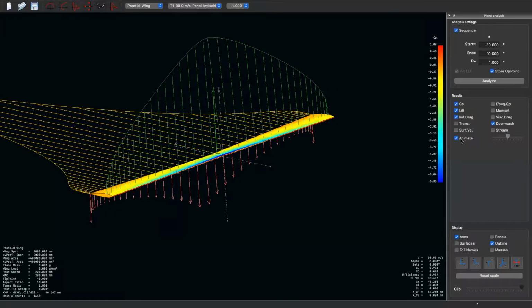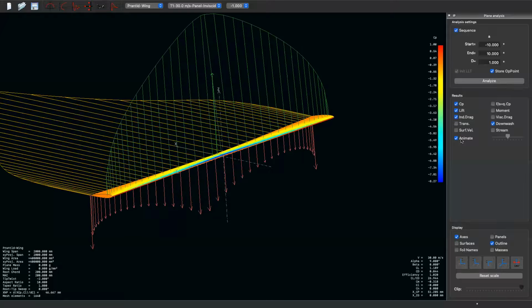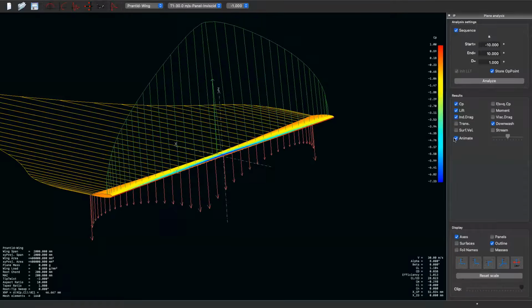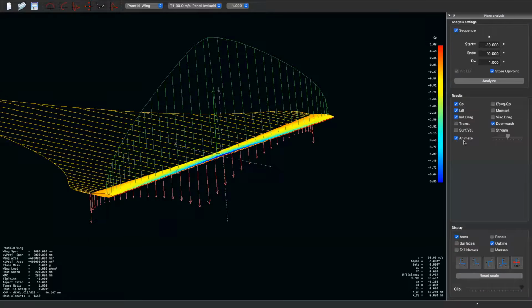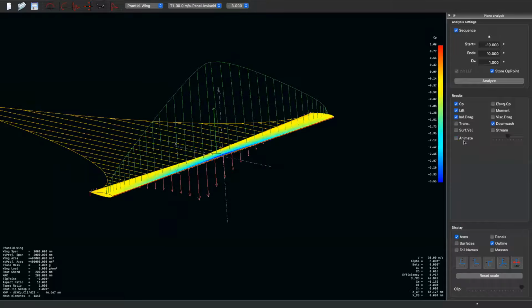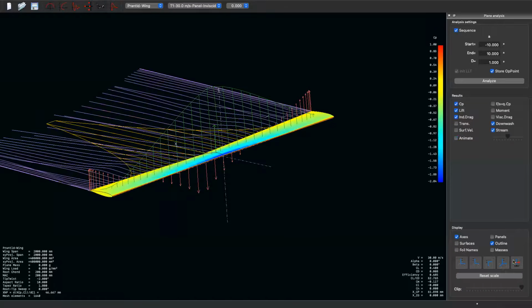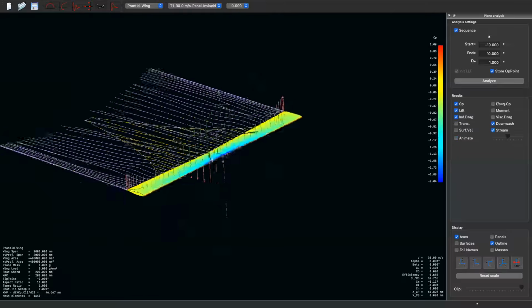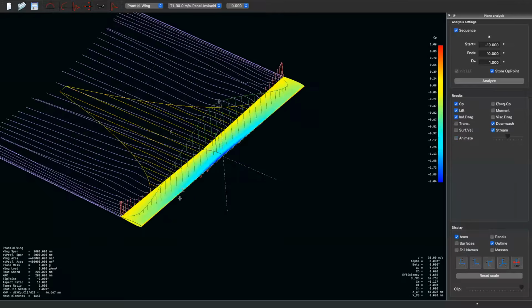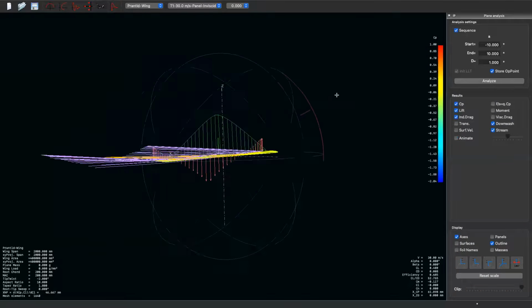So this is, in fact, pretty cool to see, and at multiple angles of attack. Another cool thing that you can also do is, I'm going to put the wing at 0 degrees. You have the induced thrust. You see the upwash on the wingtip. Now, I'm going to click stream. So that will allow me to see the flow lines behind the airfoil, behind the wing, right?